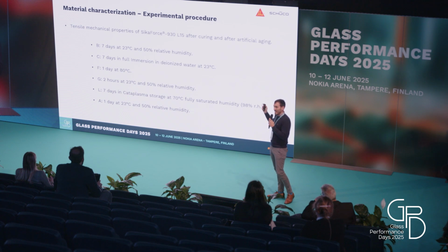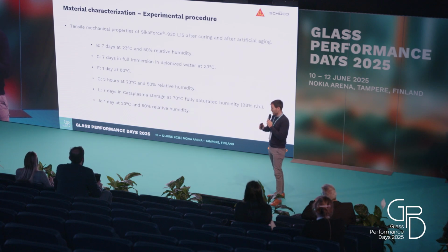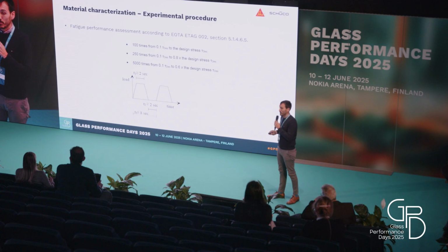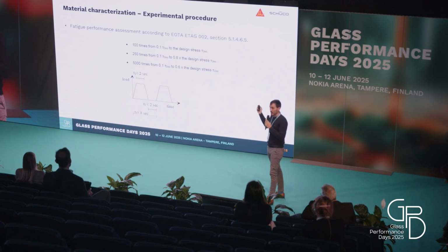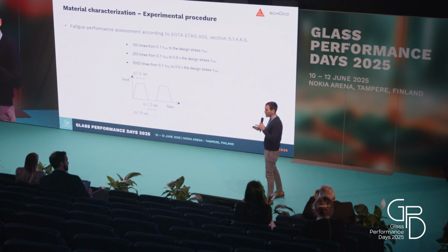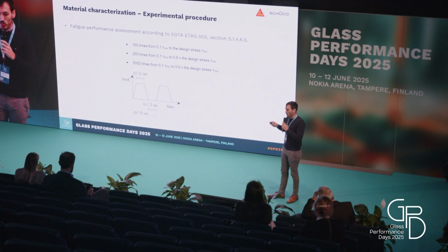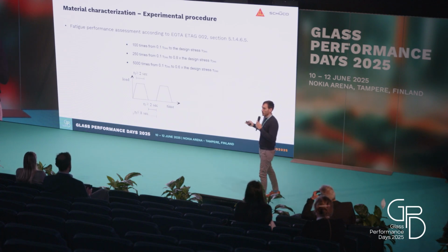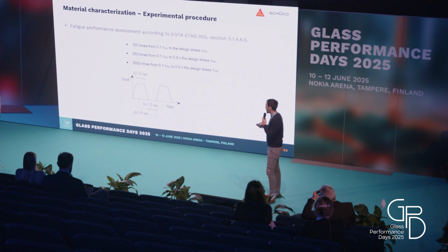So we evaluate after each one, but we only take the measurement after all of them. So we are comparing the material when it's cured with the material after all the aging process. In addition, we evaluate the fatigue performance according to the ETAC. So if we want to use it in a facade, we need to ensure that it is able to fulfill the requirements in the ETAC, or the majority of them.